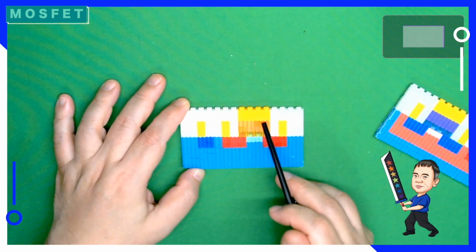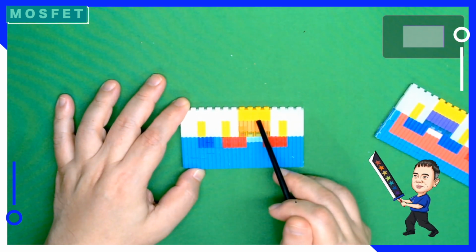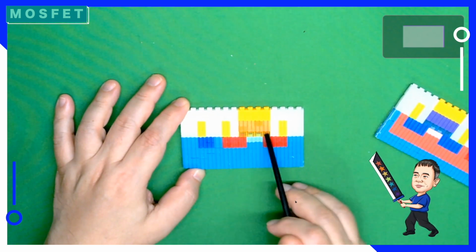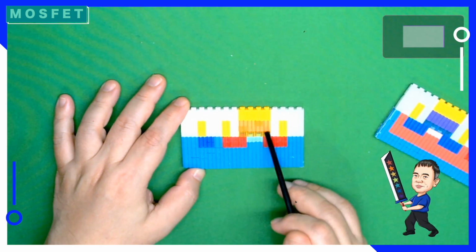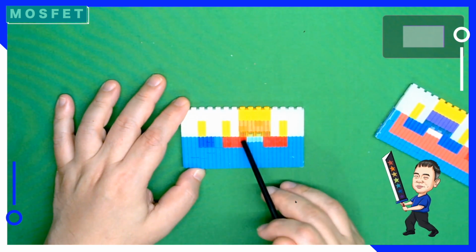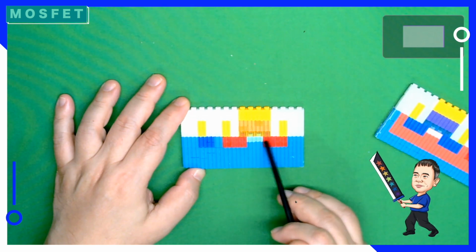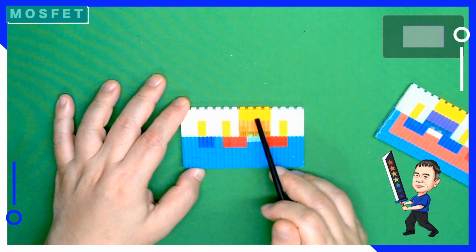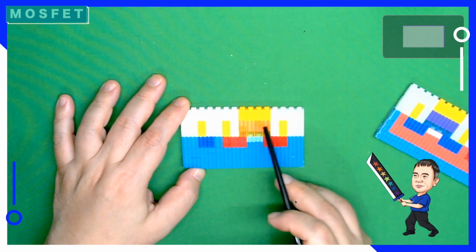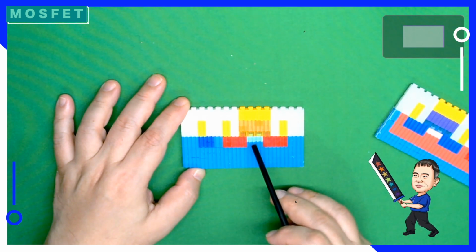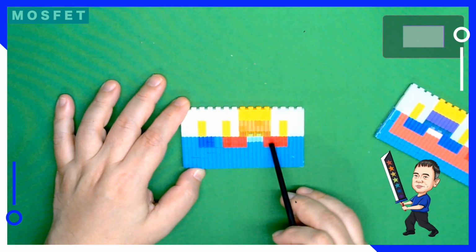What's the MOS? The metal is here, normally called a gate. Oxide is where the electric field forms, which is not conducting. The oxide part doesn't conduct current, but it forms an electric field. So the oxide part actually blocks the current, but forms the electric field, which causes the effect, forming the channel to allow the current from source to drain. So metal, oxide, semiconductor. Metal is a gate. Oxide is an electric field. Semiconductor is where the current flows.